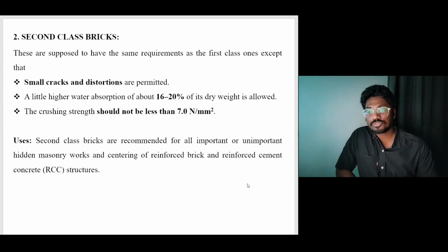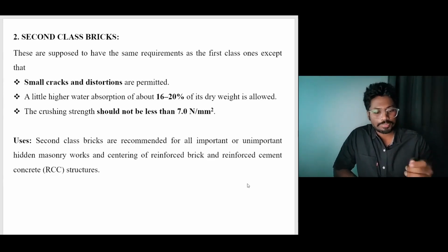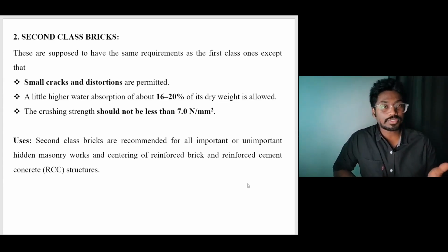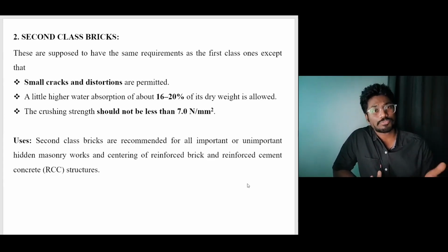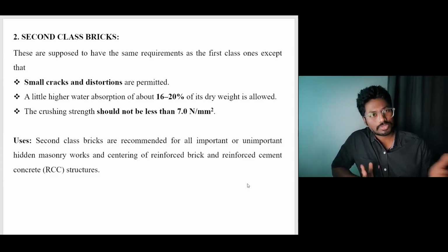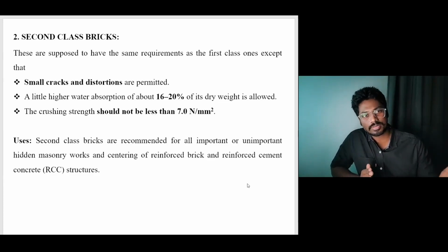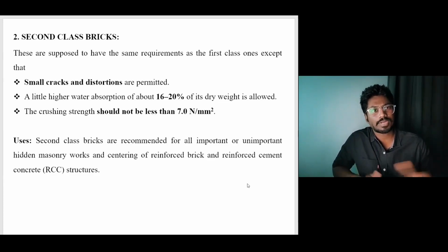Also, these are used for centering works for reinforced concrete structures. We can use second class bricks for the centering of any sort of marking that can be done. Also, these can be used for temporary structures as well. If you're planning to have a temporary structure which is not of much importance, you can use second class bricks to construct the temporary structure, use it for a while and completely dismantle it later.